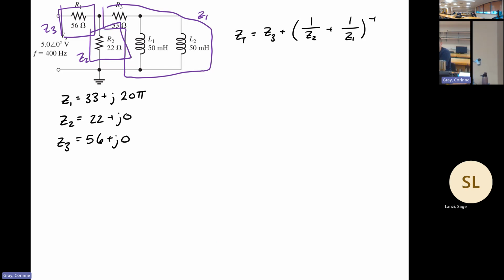So looking at it here with Z1 and Z2, and let's do Z3 as well. Let's just talk about them all at once. Do I need to convert any of them into polar? No. Why not? When you do the parallel part, it will put it back to where it won't be a division anymore. So you wouldn't necessarily need the polar form. You could put in polar, but I feel like it'd be more difficult due to it just being all addition.